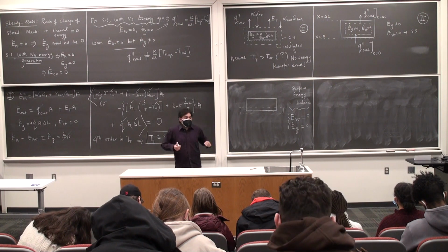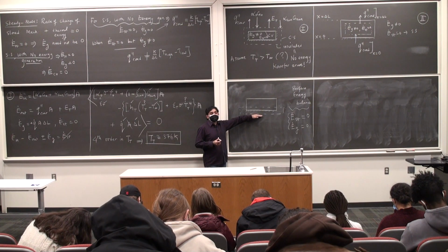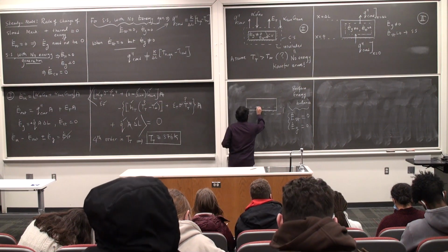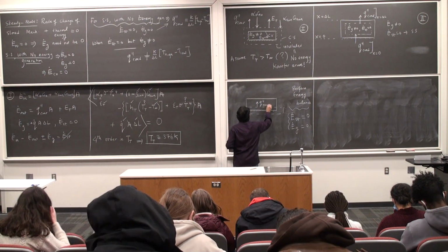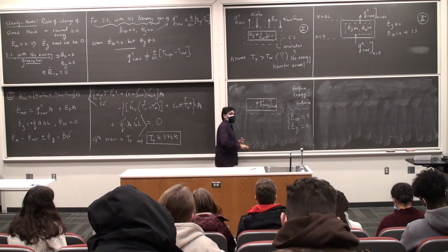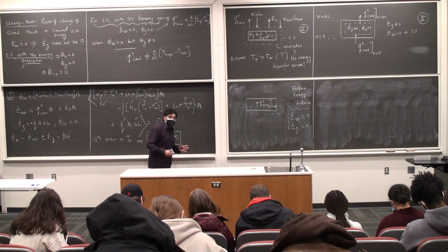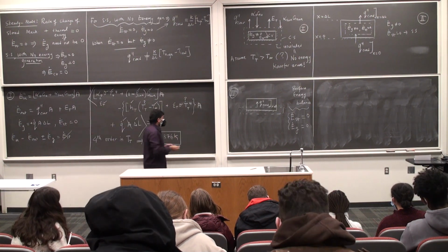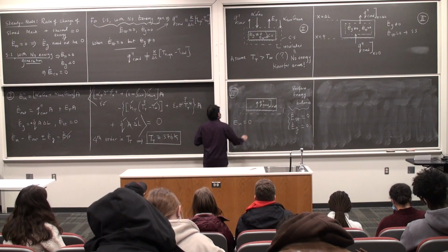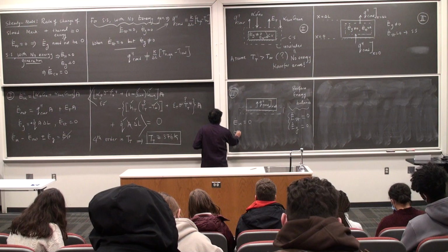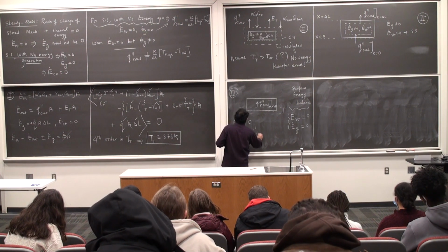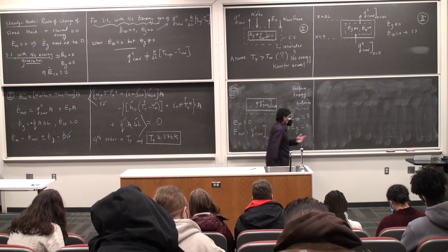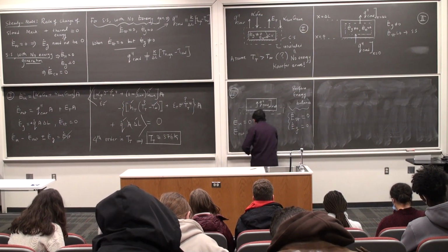Alright, now the bottom is insulated, so there is no energy transfer across the control surface here. But there is some energy transfer taking place through conduction at the control surface out there. So I'm going to draw it out as Q double prime, conduction at x is equal to 0. If I write energy balance, so this is scenario 3. E dot in, E dot stored and all that is gone. E dot in is 0, E dot out is Q double prime, whatever, at x is equal to 0 is essentially going to be 0 because of the fact that there is nothing else going on. But let me not jump.